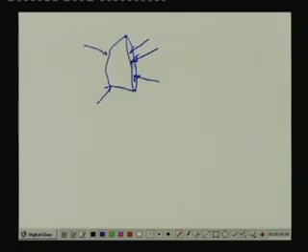One is along the normal direction of this particular cross section, and another component along the plane of this particular section. The component which is acting normal to this cross section is known as the normal stress. So, the normal stress is the component perpendicular to the particular section.